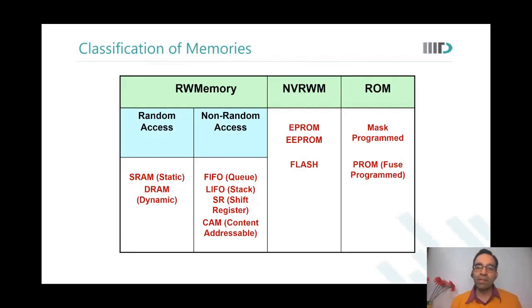So in that, what is happening is I am inside the memory doing the comparison, generating what is called a match signal, and then giving the output, considering that as the desired address. Are you able to see this? So this is content addressable memory. I do not have the address location which I want to read. I do not even know about it. But I know the content that I want to match. So I give that match content over there, and all the locations for which this content will be matched, there will be a read operation that is initiated. Is that okay?